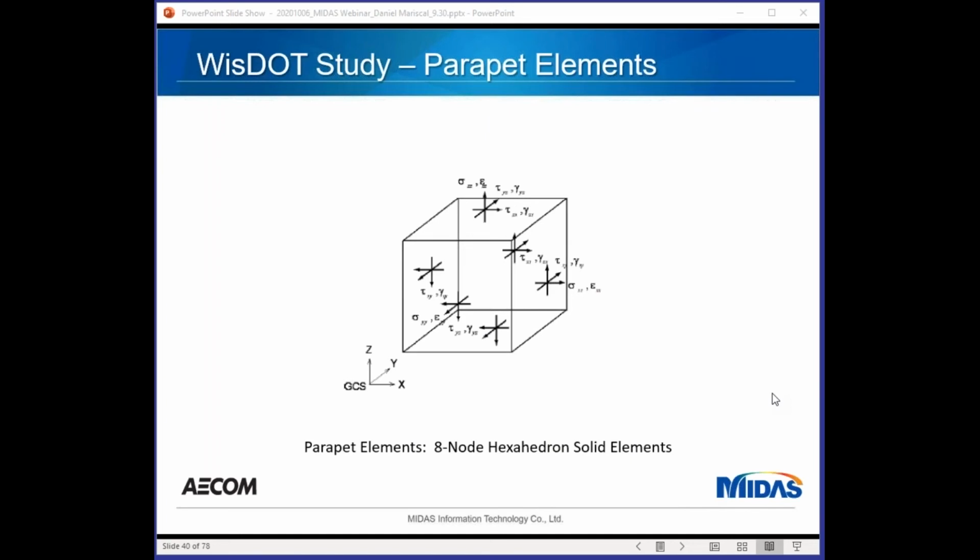In the University of Texas at Austin model, we saw, both in the pictures and in the FEA results, that the loads went from the deck to the barriers and then back to the deck further from the fracture and then back to the other girder.